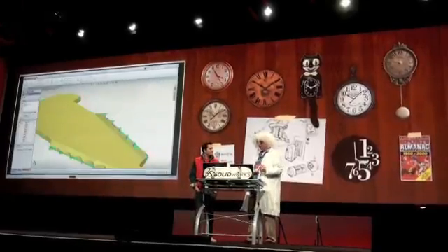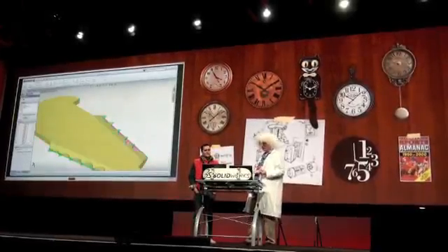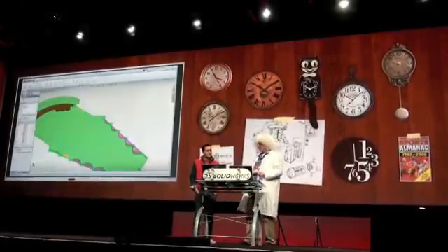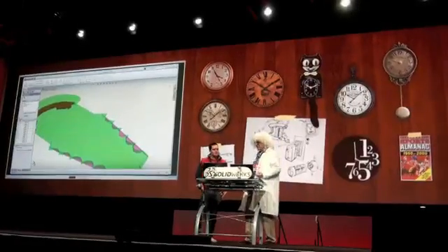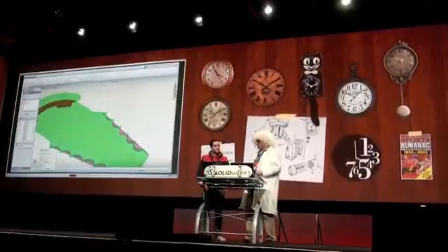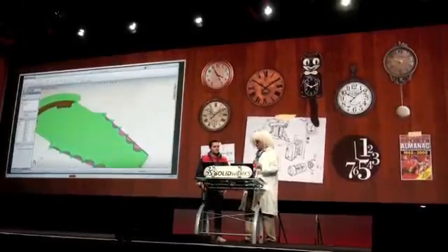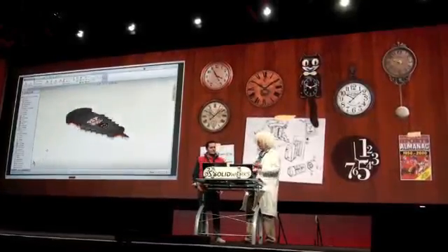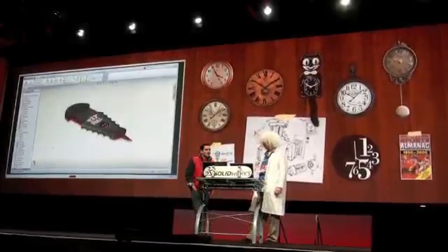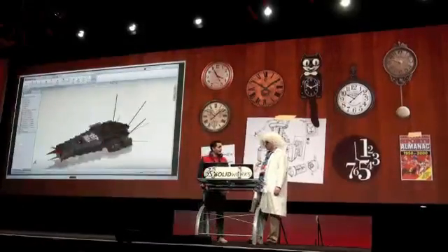Using the surface intersect tool, not only can you remove material, but add material at the same time as well. So not just cutting out the scallops, but also extending the board material to make the ends of those teeth. Just pick the body regions you don't want to keep, and you're good to go. That is pretty cool, Doc. Really going to save a lot of time finishing up design shapes.